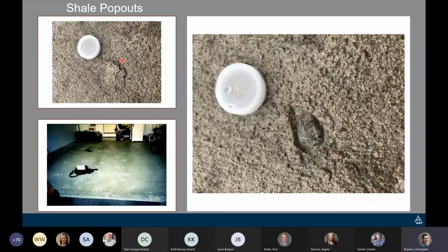So I took a photo right away. Bottle cap was the only thing I had for scale. And I uncovered the mortar flaking. That's concrete mortar flaking. I picked it off, and that's a nice big shale particle that we have up here. That's probably close to a 1/2 inch, 3/4 inch diameter.